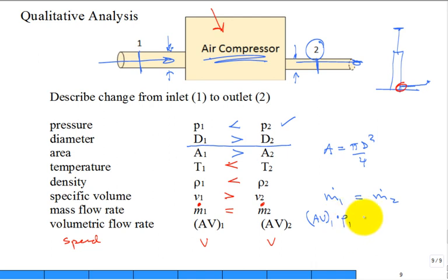Density, and then the AV exit times the density. So either the AV inlet divided by the specific volume inlet, AV exit divided by the specific volume exit, or density. Whichever, my mind probably works a little better on density, because it's proportional. I just multiply it. So what happened to the density? Didn't this go up? So what happened to the volumetric flow rate? Has to go down.